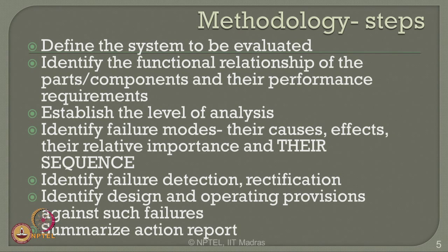Then you try to summarize your action report and give a recommendation to the manufacturer on what you suggest as an FMEA team to modify the design or to modify the operational conditions of a given mechanical or electrical system. Therefore, the failure is minimized.